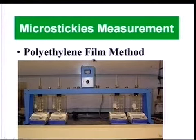Venditti and associates at North Carolina State University used the barrel method to determine the amount of microstickies deposited on polyethylene film. So in this case, you take 4 different beakers, put your pulp sample in each of the beakers, and heat it up to about 165 degrees Fahrenheit or thereabout, and put in pre-weighed pieces of plastic film. For half an hour you stir it, let the microstickies deposit on the plastic film, and then you take out the plastic film, rinse it with cold water, and measure the increase in weight of the plastic film.